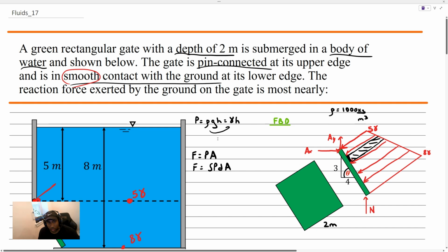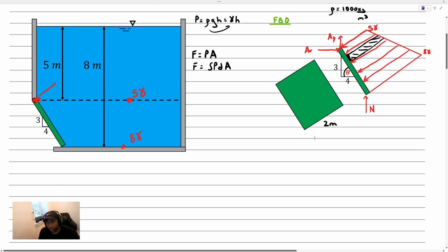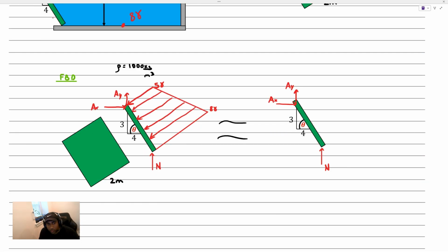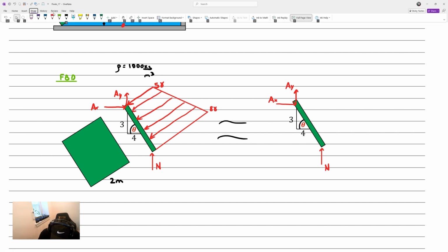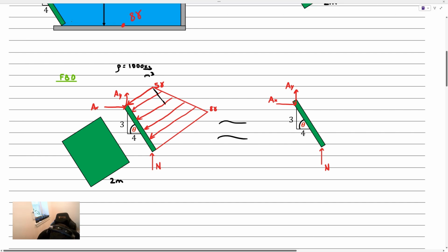So if we just wanted to go ahead and draw this free body diagram. Okay, shown on the screen here is that free body diagram that we drew on the left with the pressure distribution. And what we're going to do is think about how we can split the pressure distribution to produce forces that we can compute and whose centroid locations we know. You can see I just drew a black line here. I split it up into a rectangular load and a triangular load. And these are both prisms because they're constant in the thickness.